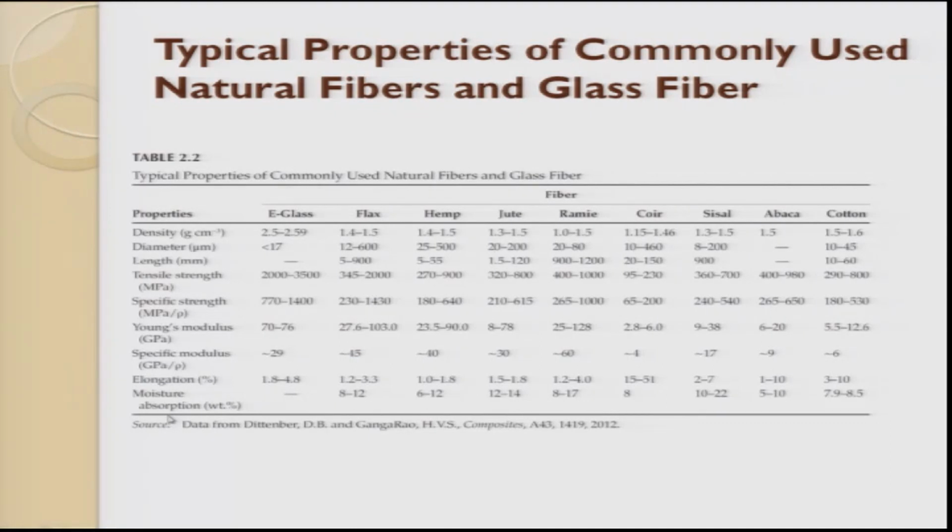Moisture absorption is one of the very important parameters which should be noted while deciding which fiber and which matrix to choose, because the moisture present in the service condition tries to dictate the performance of the composite.